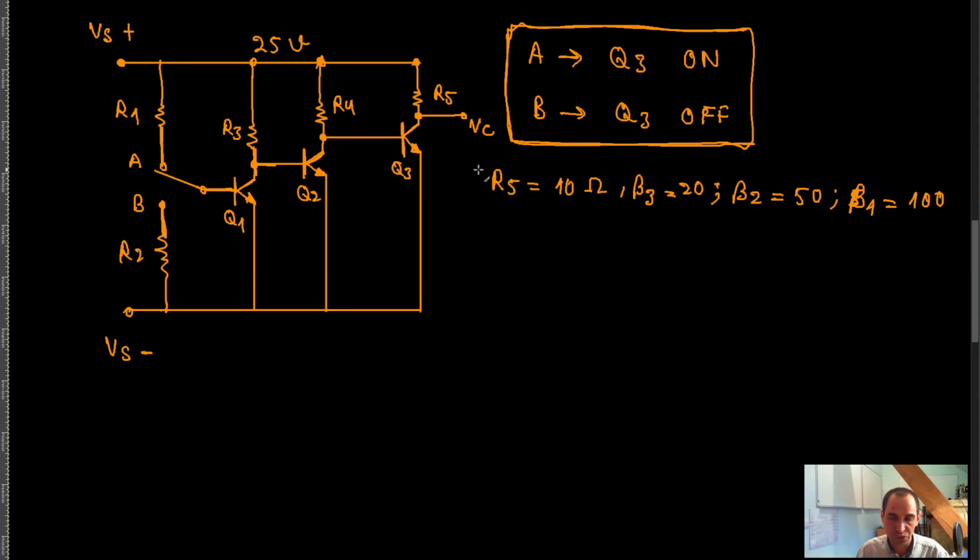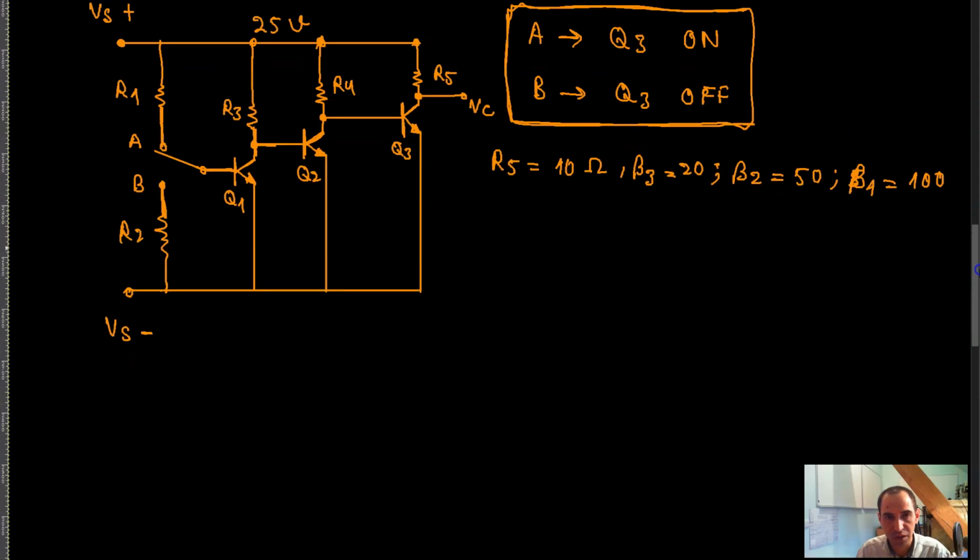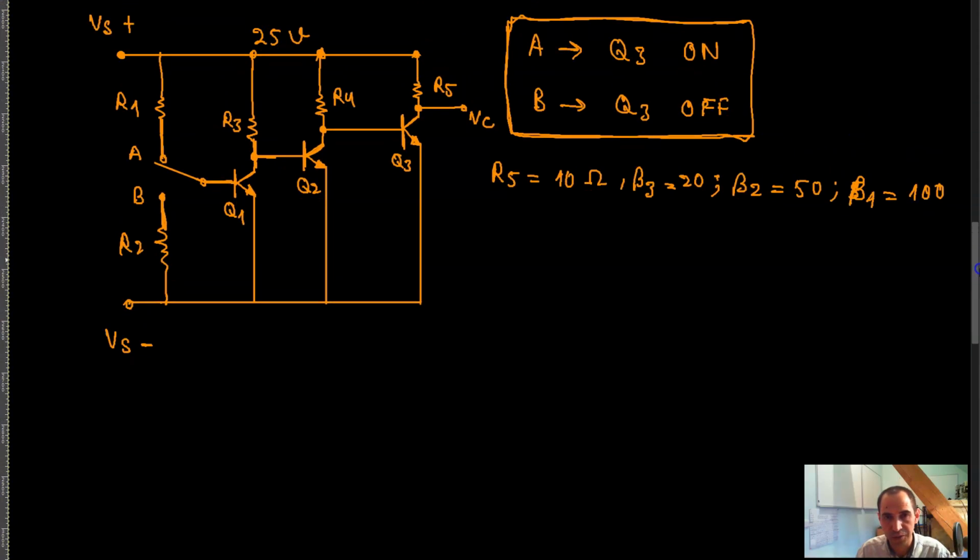Of course you could choose another resistor, that's not a problem, but let's suppose that we cannot change this resistance. By changing the current that goes through the resistor, I can change the voltage drop across the resistor. Normally you cannot do that, but the transistor basically enables you to do exactly that, which is something very interesting. I never actually thought about it this way.